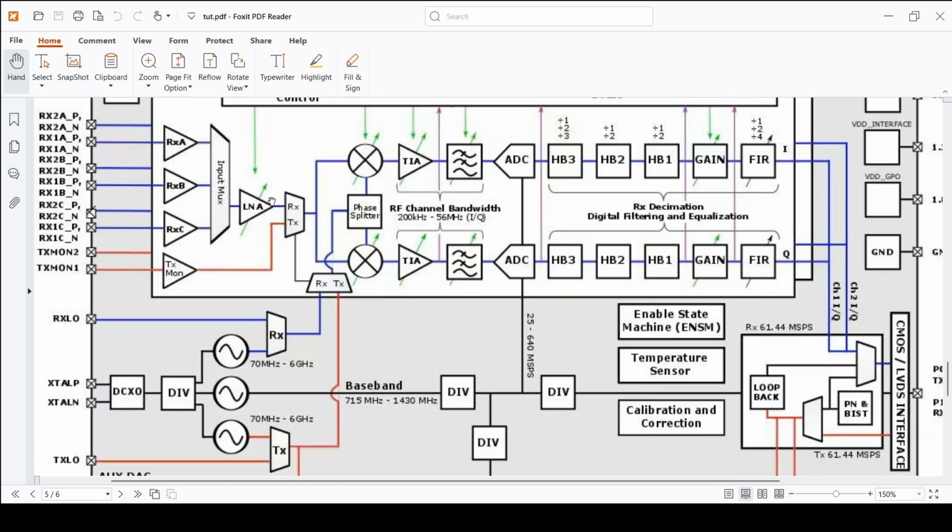It multiplies the input received signal by a sine of f and a cosine of f, and then sends it to the ADC and sends the information back to the RX buffer, where we can apply very accurate and very powerful low pass filtering. The accuracy of this down mixing is determined by how accurate the LO frequency of this mixer is, which is set by these oscillators inside our ADALM Pluto.